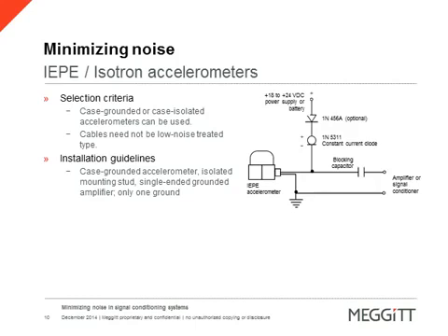IEPE sensors are either case-grounded or isolated, so the proper one should be used with the signal conditioner that can match this system, being a single point ground system. The diagram to the right does not clearly indicate where the ground is. It should be either at the sensor or at the signal conditioner. I just wanted to point that out because that's not really clear in that diagram, which is depicting the typical connection for an IEPE sensor.